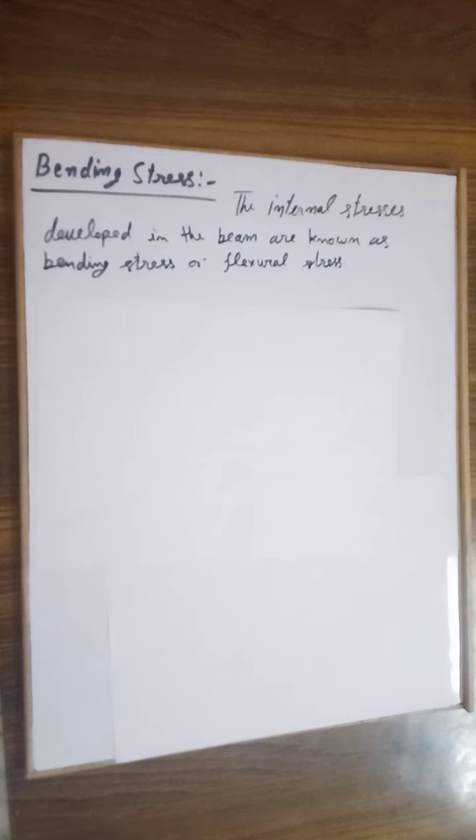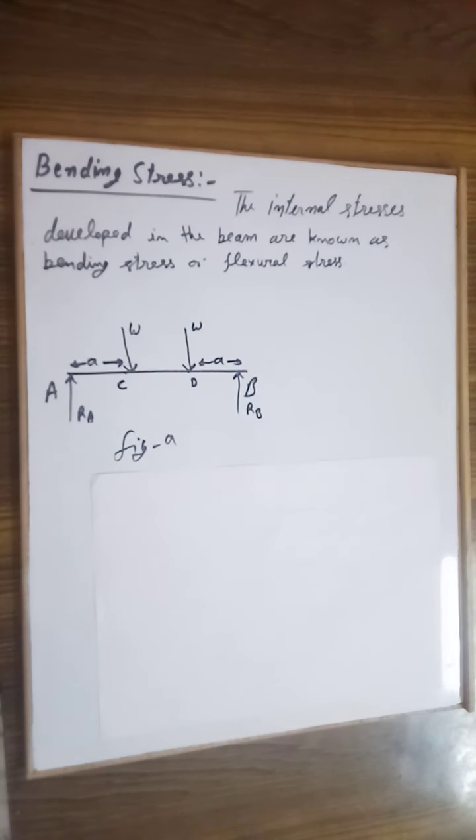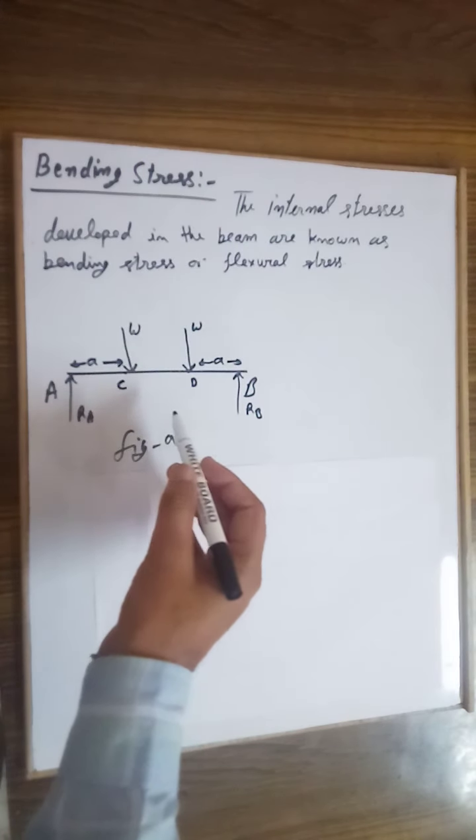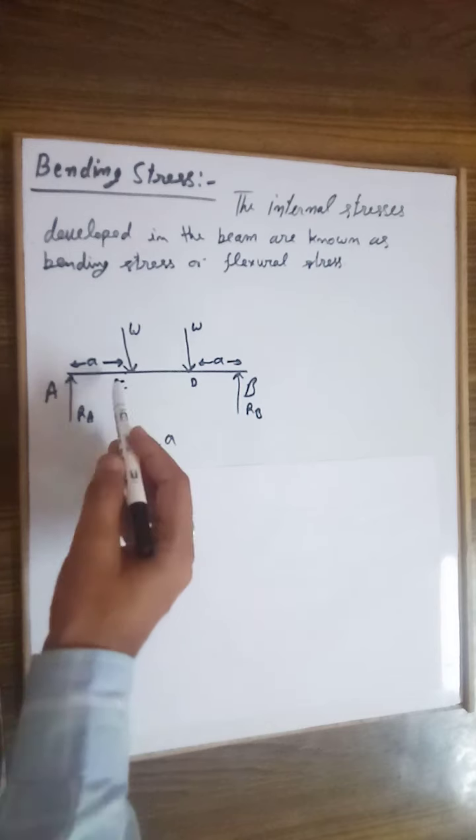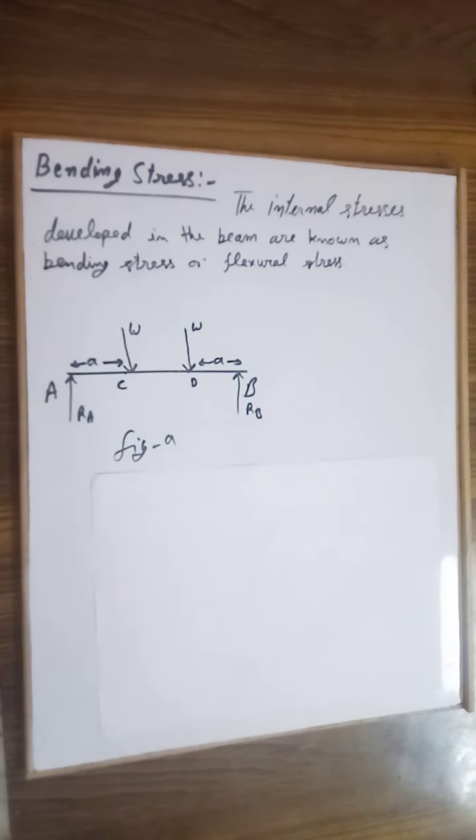So to understand this, we need to draw a diagram, a figure. So let me draw the diagram first. Here it is, in the figure. Here it is displayed. The portion CD of the simply supported beam is under pure bending, as there exists no shear force.